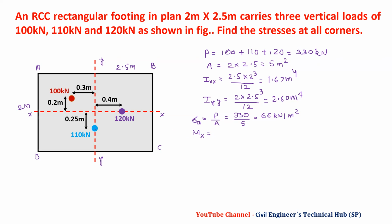So we have more moment due to 110. So we have compression on C and D due to Mx. So we have 110 into 0.25 minus, because one will be clockwise, another will be anti-clockwise, minus 100 into 0.2. And we have this value, 7.5 kilonewton meter.